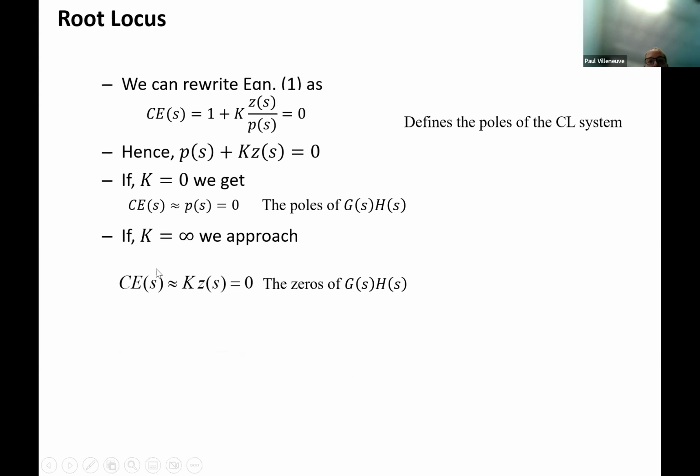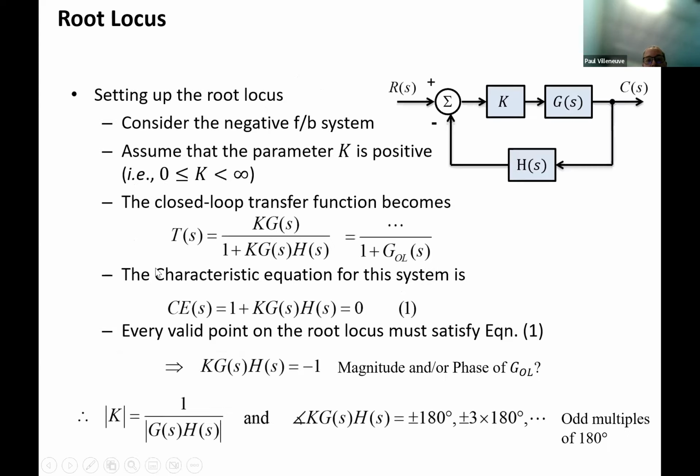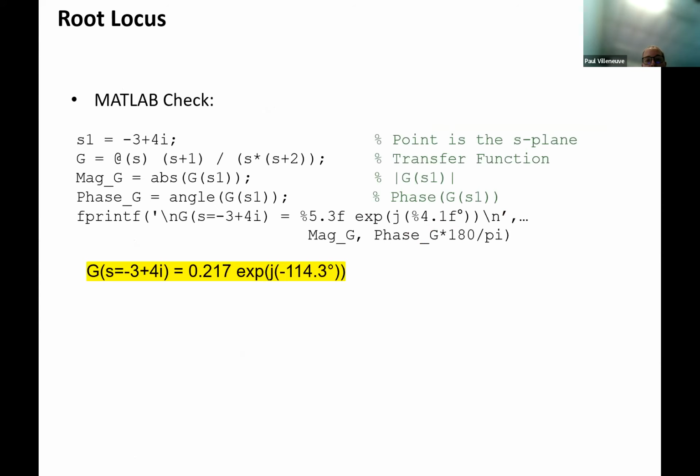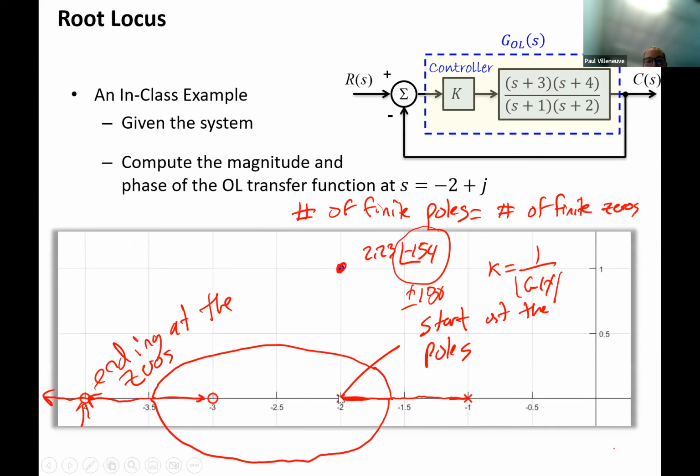So that's why when you look back at this plot here, I started at poles. I didn't show the arrows, I should have, but I'm going away from my poles, and I did show my zeros here and here. So this one is going up in this direction, going down in this direction, and continuing until it gets back onto the real axis.